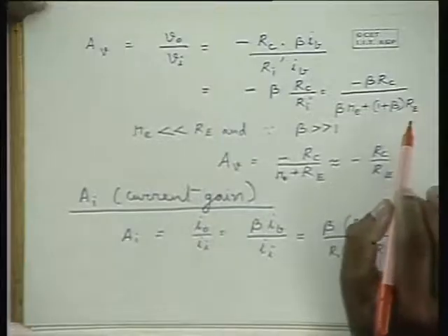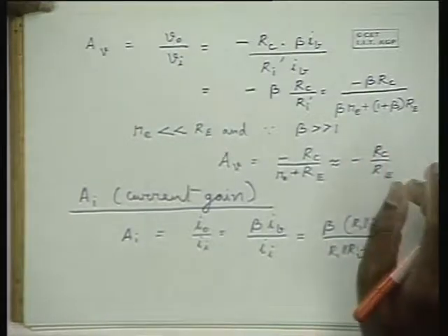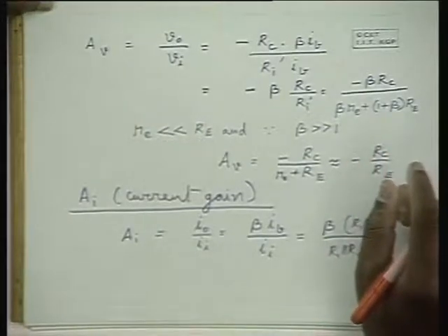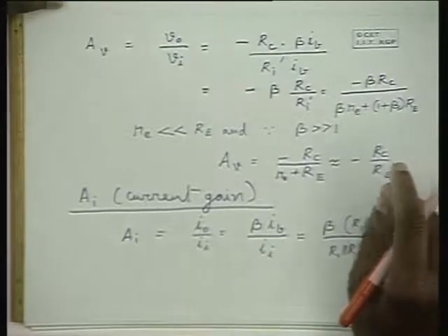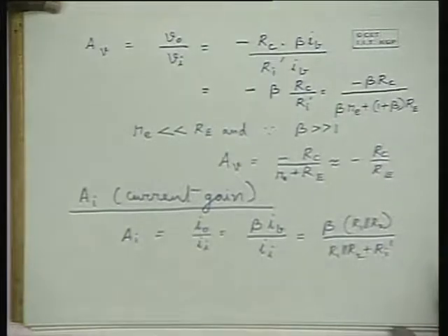Yes, it is possible. That is how feedback is provided through a small emitter resistance Re. Some feedback is provided, and through that the stability of the voltage gain and current gain, etc. are maintained in practice. Yes, it is a usual practice of feedback amplification.